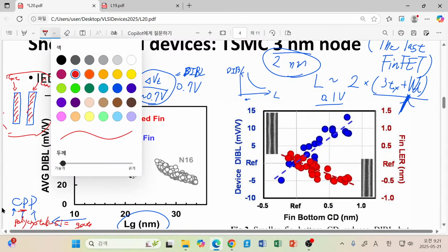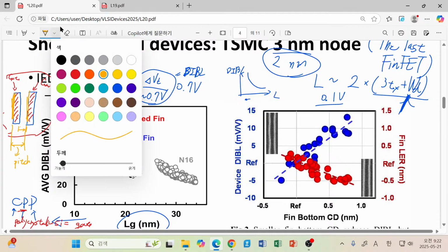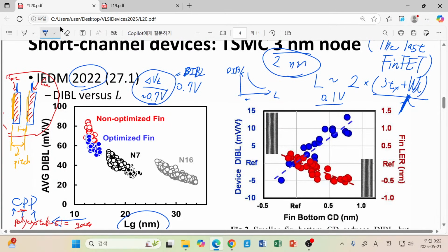Then what is the actual value shown here? Is this the distance between these two lines? Actually not. The pitch in this case is the distance between the same pattern. So we have to have this length as a pitch: the left end of our gate pattern and once again the left end of the next gate pattern, or usually we just take the middle of a gate pattern and the middle of another. They are taken as the reference plane for our pitch calculation, but which one is the reference doesn't matter, because when they are periodic, every position can be used as the reference plane.